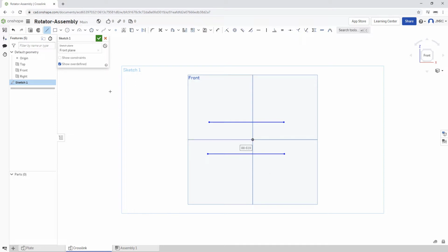Let's create an arc, heading up, selecting this drop down, and let's select 3-point arc. Let's drop the first point at this end point. Next point here, left click, and notice the inferred tangent constraint, left click. Creating another arc, left click here, and left click.